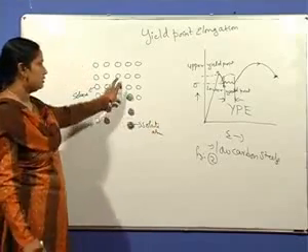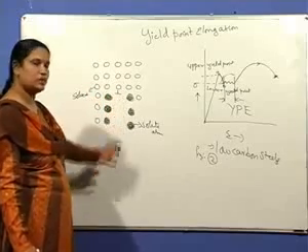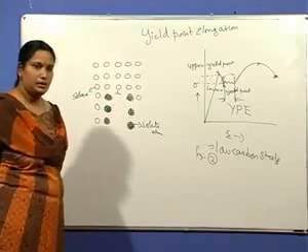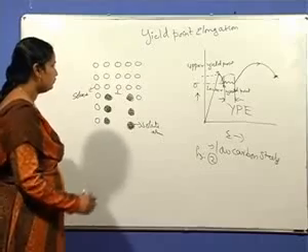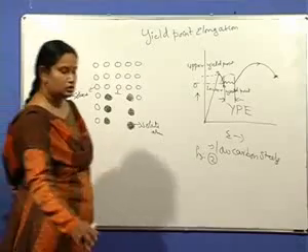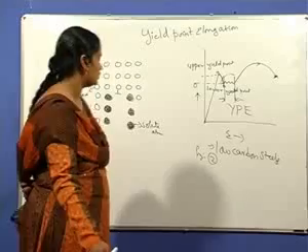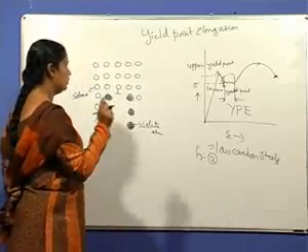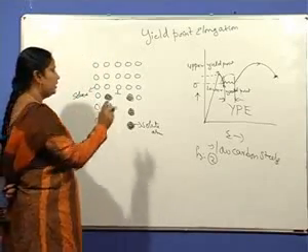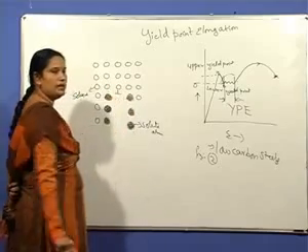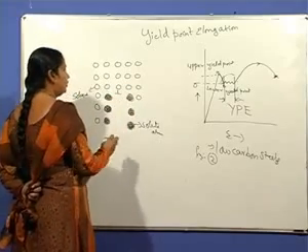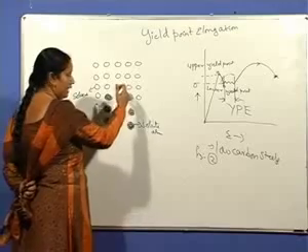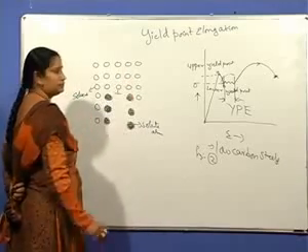So this is the edge dislocation. Below the edge dislocation, the slightly larger solute atoms occupy the positions. Whereas if the solute atom is slightly smaller than the solvent atom, then they occupy the positions above the edge dislocation.